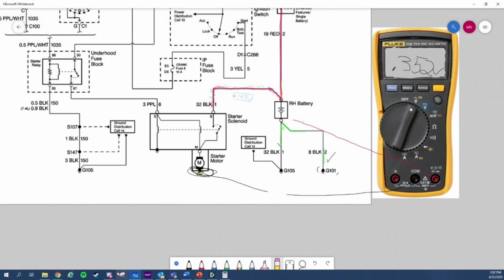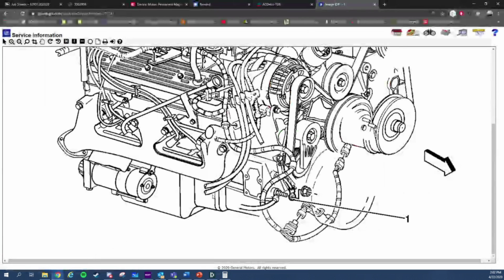So think about it, guys, really think about it. If this cable is attached to my battery and if this is loose or corroded or has high voltage drop, do you think my starter is gonna get a good ground? No. So can that be a big problem? Yes. Can you send a picture on Discord? Yeah.